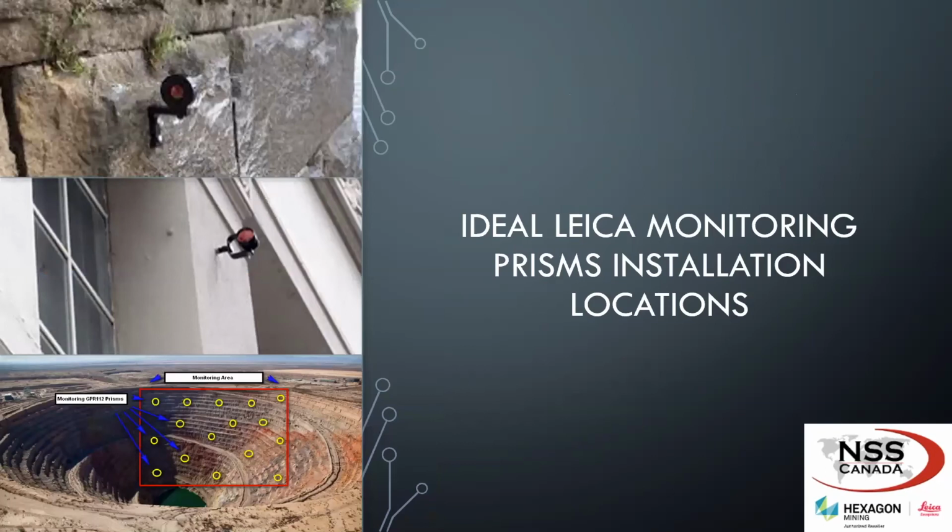So, the ideal Leica monitoring prism installation location. Now we're going into the monitoring prisms. The first ones I just talked about were the reference prisms. These are the monitoring prisms. The Leica GeoMoS monitor requires the monitoring prisms to be installed within the monitoring project, not on the outskirts like the reference prisms. The Leica monitoring prisms should be installed in areas of key operations, ground stability issues, highly active working areas, or areas that can pose a risk or a threat to individuals and or equipment.